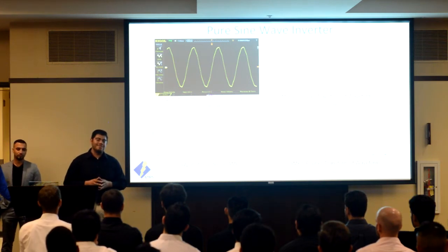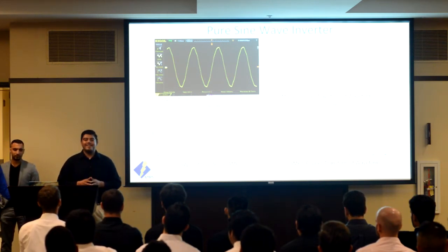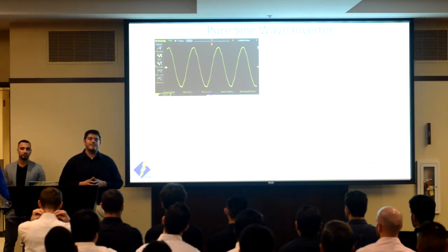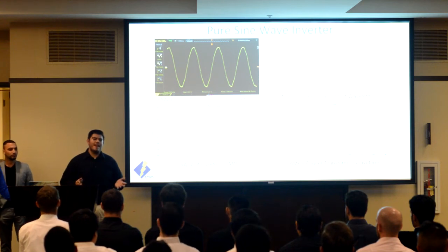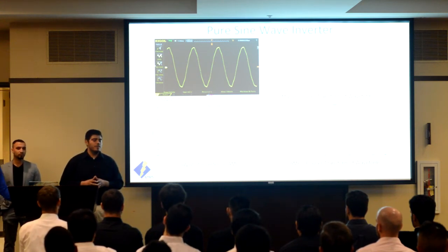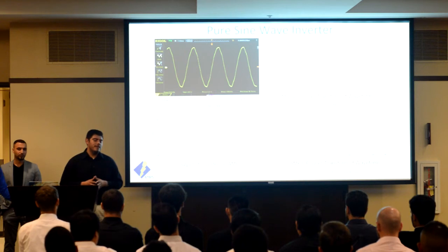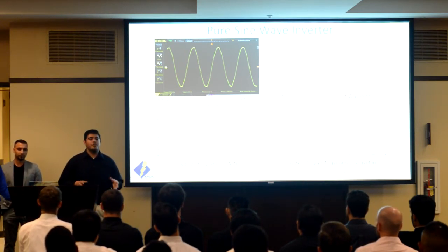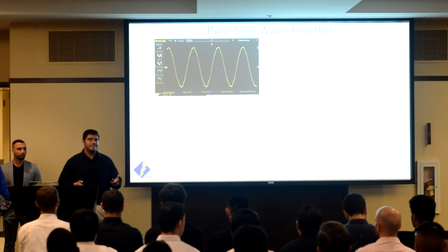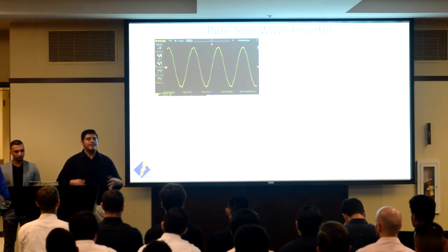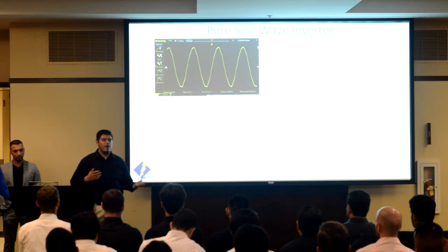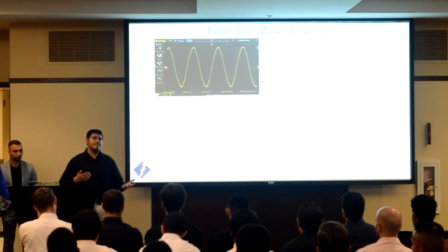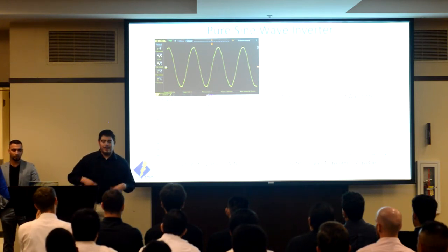And let's say you want to be kind of cheap, so you decide to get a lower quality inverter. Well, the drawback with using that lower quality inverter is most likely it will produce a modified sine wave output, which will create more harmonic distortion in your system. In turn, as mentioned before, this will increase power dissipation in your electronics, shortening their lifespan, and in the long run, it's going to cause you to swap out whatever system it was in sooner. So you may save some money up front, but it's going to cost you more in the end.